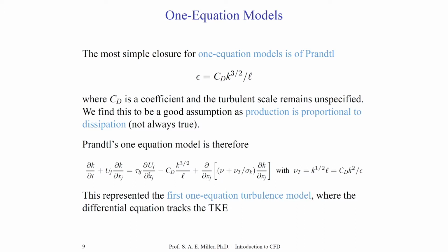So now, really, what don't we know in this equation? We don't know k, but that's the equation which is representative. That's the variable we want to find. It's now a field variable, the turbulent kinetic energy. We don't know the mean values u bar, but those, of course, are shown in the momentum and continuity equations, etc. We don't know tau ij, but that's just the stress tensor.